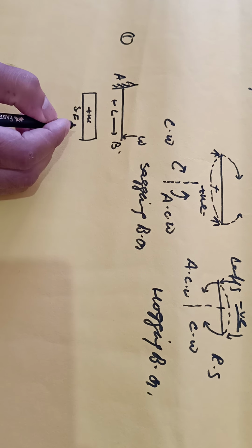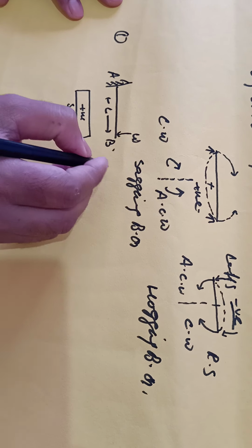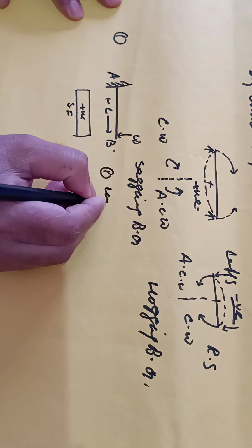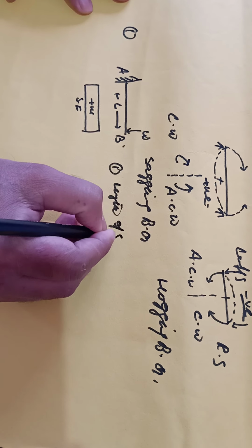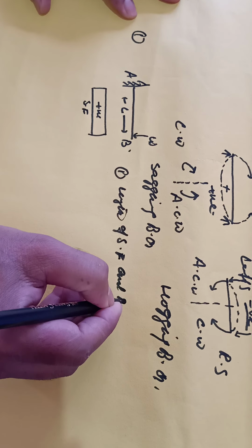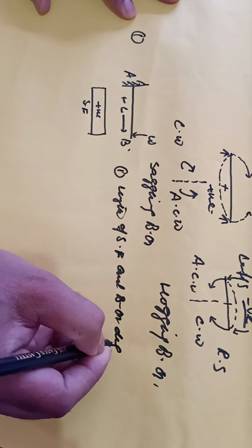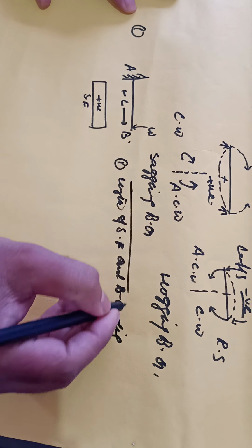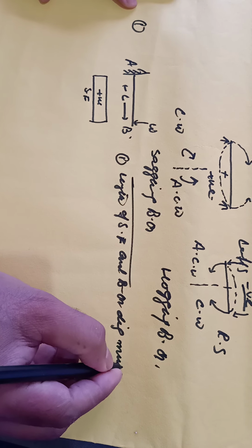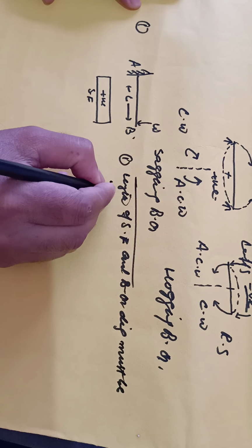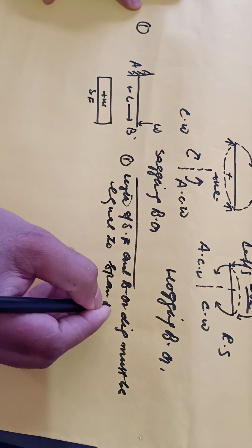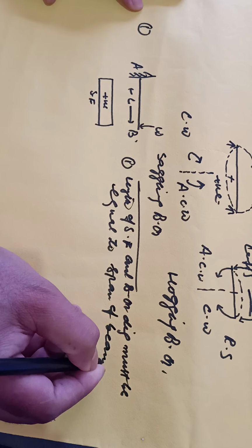Number two, I will write down here: the length of the shear force and bending moment diagram must be equal to the span of the beam.